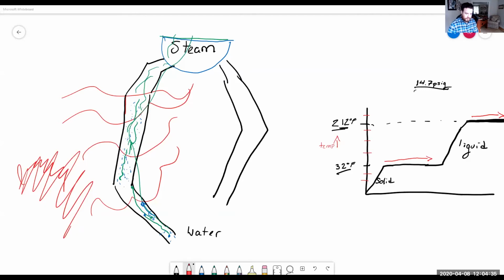So, next, we have what's called our superheater. All right. Our superheater is located in between our generating tubes. Okay. And the big thing to recognize with them is why they're there. Why are they in between our generating tubes? If we want to make sure there is no steam and no water molecules inside of that superheater tube, why not just have them right on top of the flame?